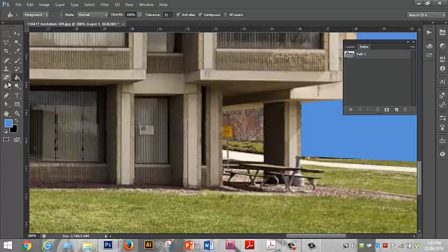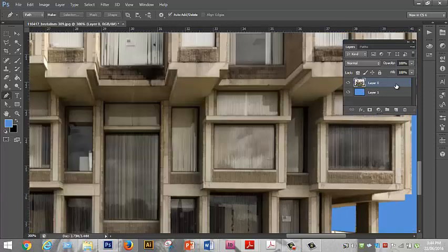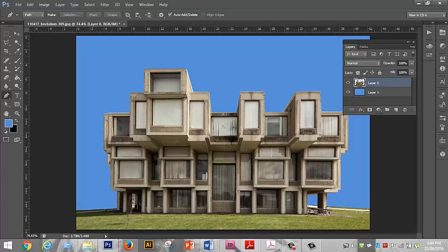Now I want to make another path, so I'm going to go to here now, and I'm going to line up with that. Right, so I've made a new path. Let me turn it on and make sure I'm in the correct layer, layer 0, and delete. Control D to deselect, and let's go back out. Control 0 gives you the maximum view. Okay, we can now proceed to the next stage.